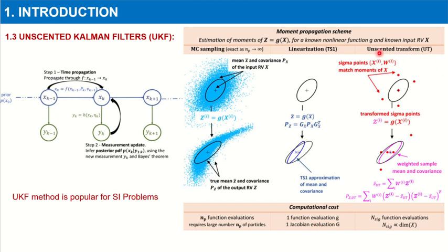The last method is the Unscented Kalman filter. In this method, we use some sigma points, which are symmetrically and elliptically generated, so that the mean of the sigma points is the current state. With the sigma points we calculate some sigma observations, and finally we can update and predict the state and the covariance of the state based on the sigma observations and the sigma points.